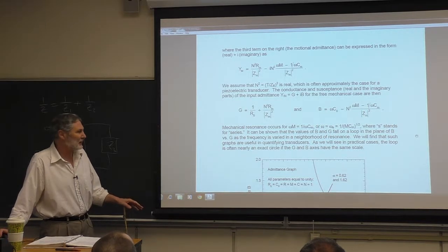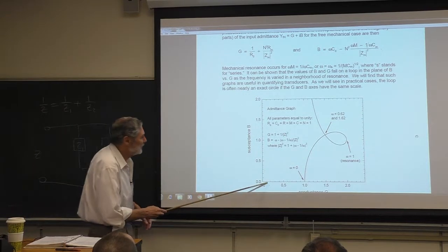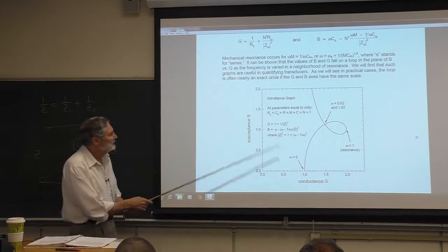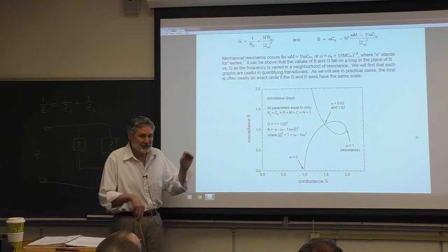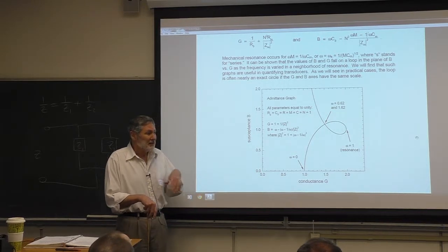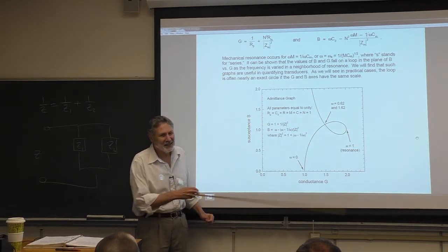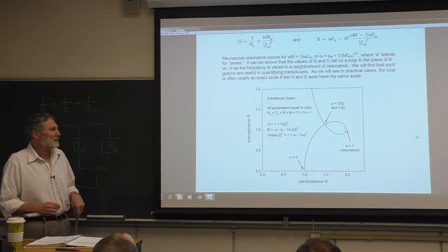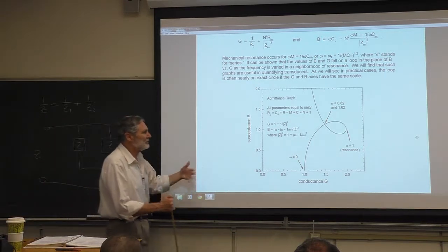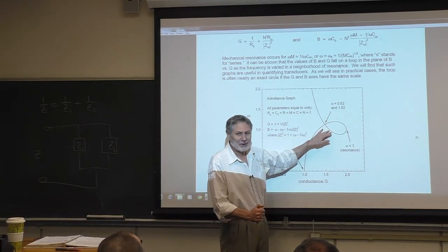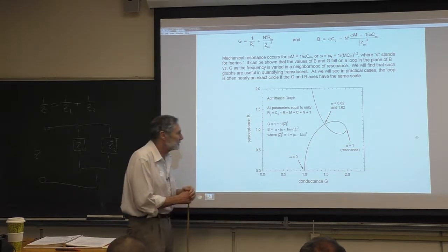So I finally just bailed out and did a plot. So this is my plot here of the real part of the admittance, the conductance, versus the imaginary part, the susceptance. And what I did here, because I was just after the pure mathematical statement, is, are these really circles? Well, no, they're not circles, okay? This is not a circle, right? But for typical sonar transducers, and I don't really know why, it ends up being really close to a circle very often. It's not exactly a circle, as you can see from here.